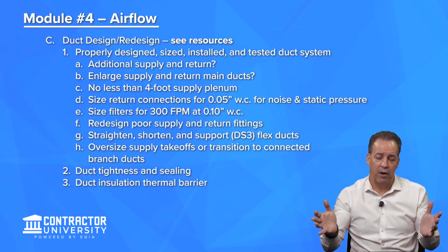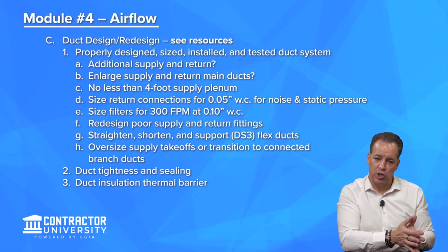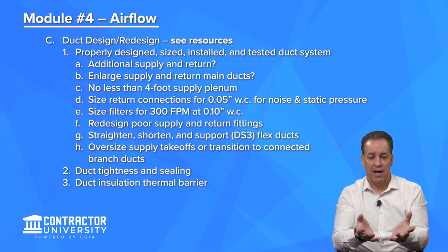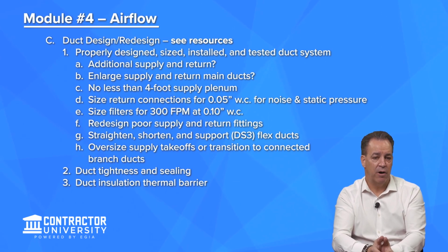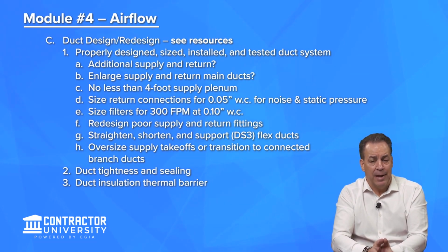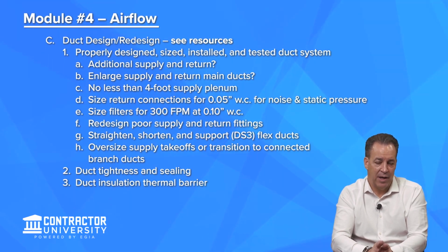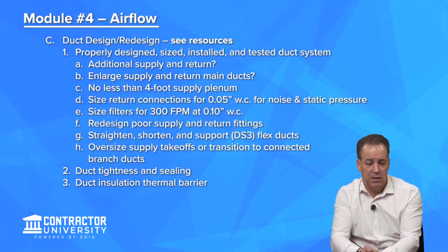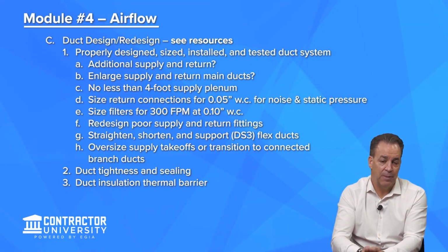You're going to, again, inherit ductwork that's probably going to have R2 or R4 insulation on it on the outside of it. Or it might be flex that's insulated with R2 or R4. Again, I'd recommend upgrading that to R8. It's a hostile environment. Odds are it's in the attic in most cases, that you're going to find insulated ductwork. Ductwork also should be insulated when it runs through any unconditioned space, such as a garage or a crawl space. If it's a heat pump, the ductwork supply and return should both always be insulated, in my opinion.